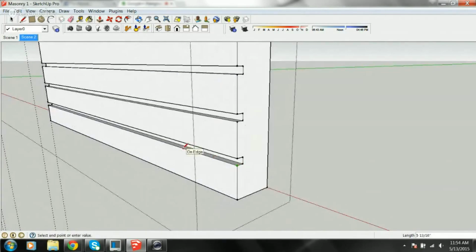Okay, well, standard brick width is going to be 8 inches. Well, I'm not doing 8, 8, 8. I'm going to do 7.5 and a half-inch mortar joint. The reason I'm using a half-inch mortar joint, and this is trial and error, I haven't sent one of these off to Shapeways to print yet, but when I calculate their minimum engraving detail, when I'm working at full scale here, what I've determined is that a half an inch is about as far as I can go down and have it be engraved.